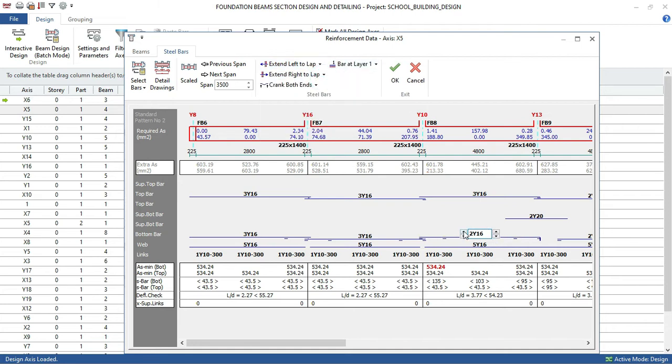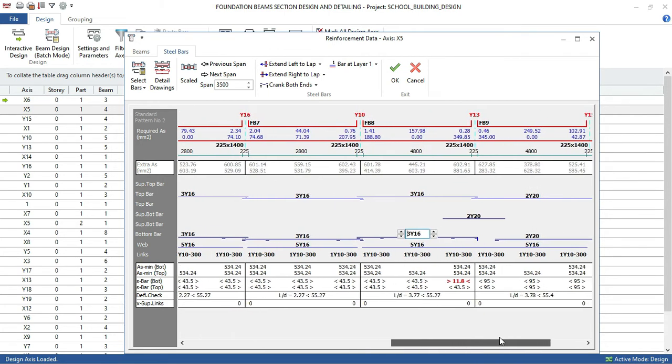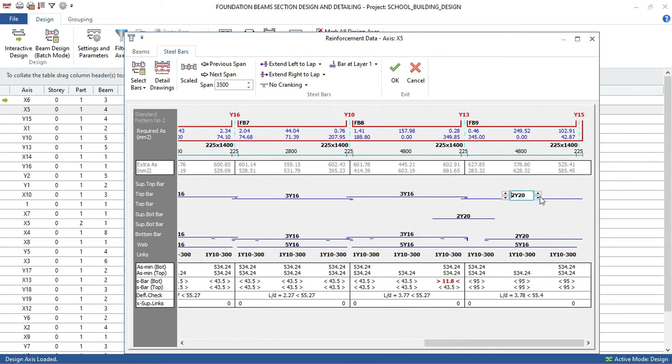Okay, so now you have to increase the number of reinforcement here again, and then go and check again on this place. Come here, decrease the diameter, and then increase. When you decrease, there will be a failure. This rating here means failure. If you go and print out your drawing like this, the building will collapse. So you have to increase to make sure that there is no red here, and also no red here.